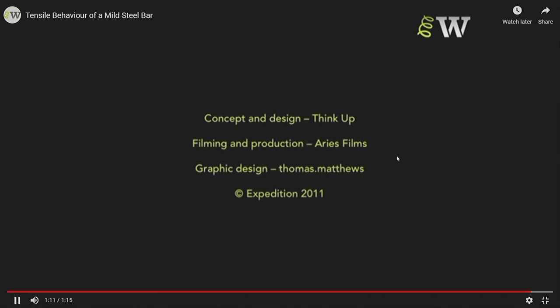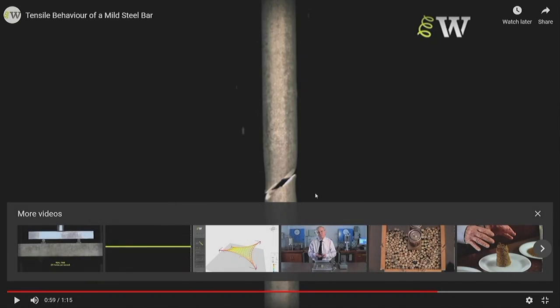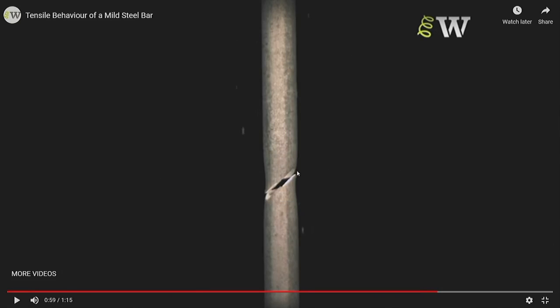Okay, so interesting things to note here are a few. One is you could see the failure happens at about 45 degrees roughly to the length. So it didn't snap off. Isn't this 45 degrees because of propagation of, I think, something like cracks along the planes of principal shear? Because the planes of maximum shear are 45 degrees to the direction of the loading.